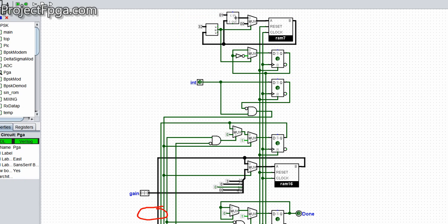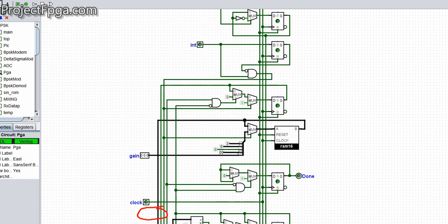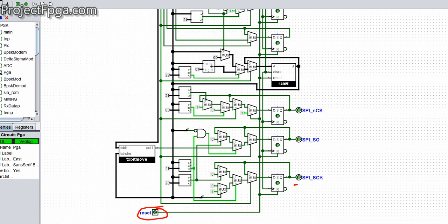After the generation, it comes out here. That clock is the clock that will be used for this SPI down here. The SPI clock, that's what we generated up here, is almost the same as the TS clock. The transmit clock is 4 megahertz for this particular circuit, and the SPI clock is 2 megahertz. But this is how we generated it.